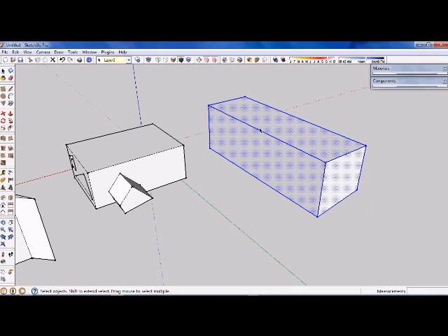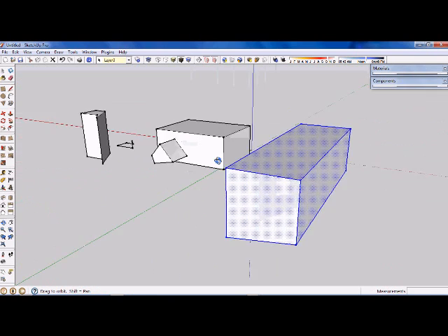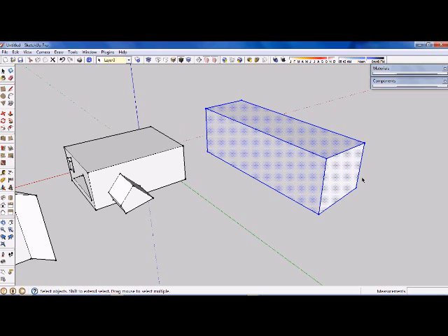If you can imagine that if they were metallic objects, anything that might have an electrical connectivity to any other side of the object there, they are all selected in one go. Any of these objects here that are separated by an air gap to that geometry did not get selected. So I can now hit the delete key.